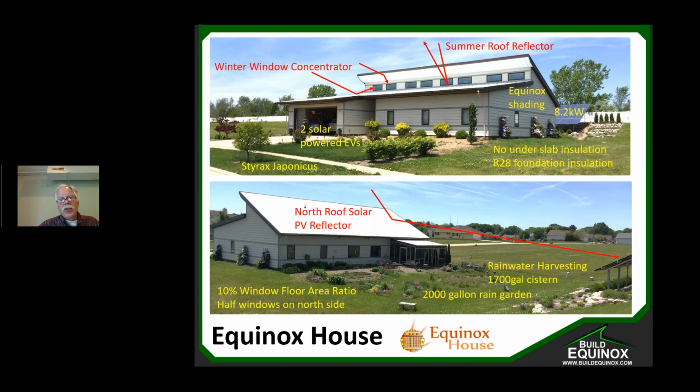But we did put these things in, such as what we call the Equinox overhang, that takes low altitude winter sun rays and concentrates them into our clerestory windows off this 2-in-12 pitch roof and this uplifted Equinox overhang. And then summer sun, relative to this 2-in-12 pitch roof, is reflected back out into space as well as not allowed to go into the house.